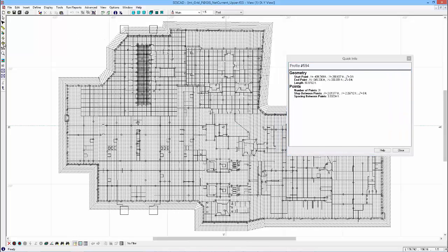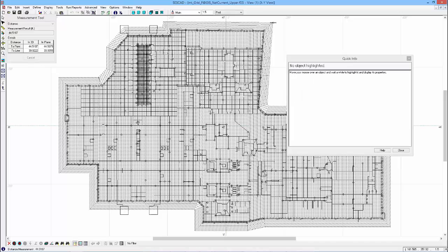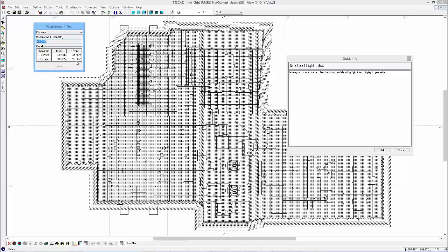In fact, we can measure exactly how far out we're going. The measurement tool here. So we're going at least 44 feet out from the outside of the grid. For touch potentials, we'll probably be reporting only up to 1 meter outside any conductor that can be touched, like 1 meter outside the fence. For step potentials, however, it's important to know that the step potential has gone down a prescribed limit even as we walk away more than 1 meter away from the substation fence.